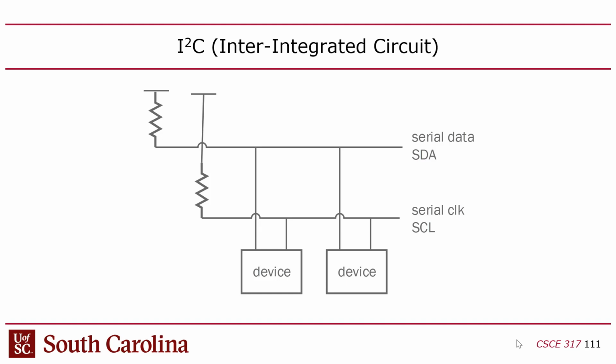And so we're going to look at this I2C, or sometimes I-squared-C, or sometimes you actually say I2C. It stands for inter-integrated circuit. Inter meaning it's designed for chip-to-chip communication. And it uses an open drain style, right? And it does that so it can be a multi-master, so that anyone could take mastership of the channel. Anyone that wants to be master can be master. Make sense?